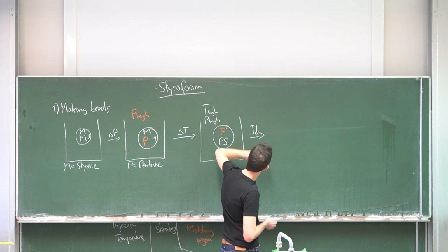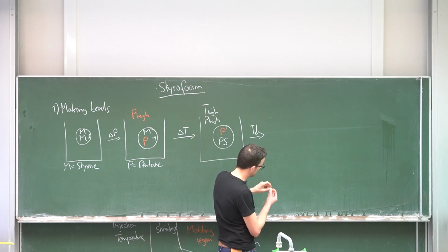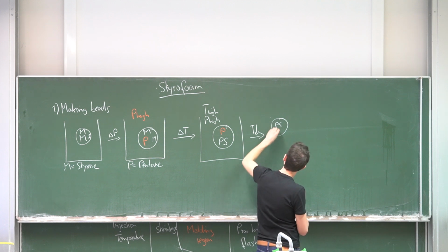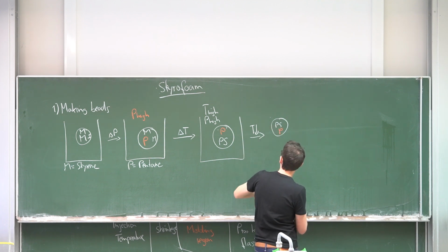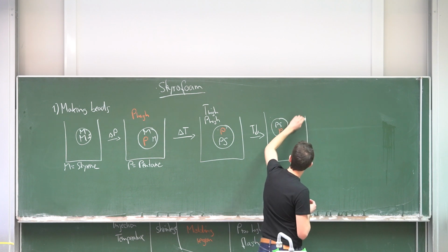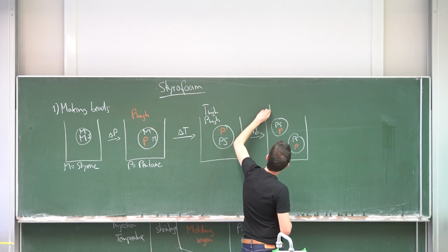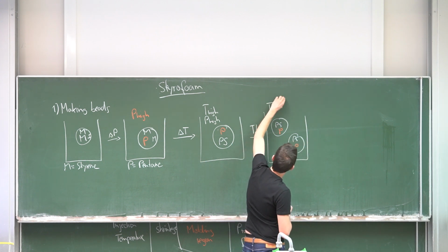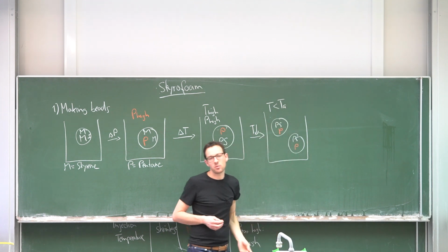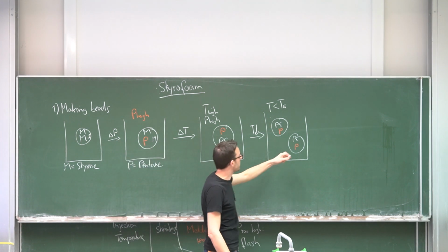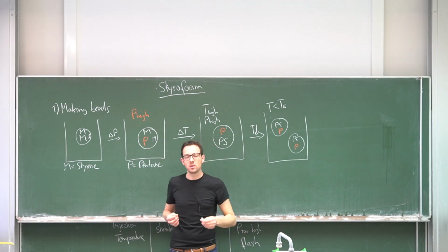And now we cool down and we remove our continuous phase. Hang on, so first maybe we cool down, and as we cool down, the temperature is smaller than the glass transition temperature of the polystyrene, and that means that we efficiently now trap the pentane within our hard material.